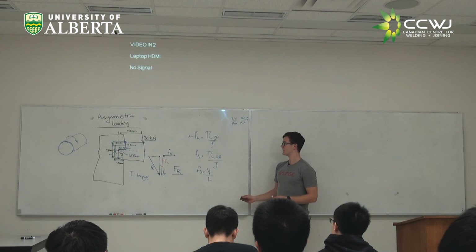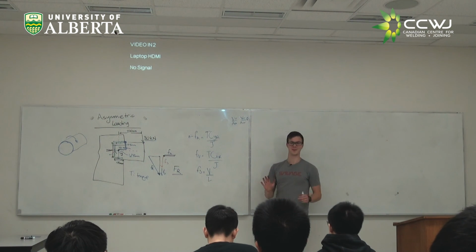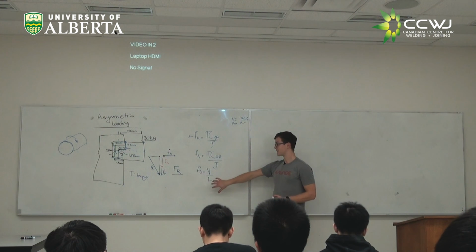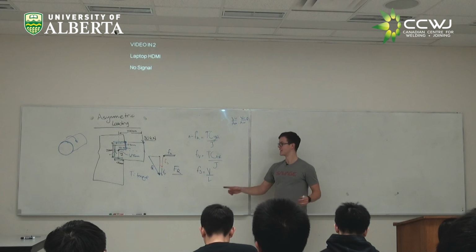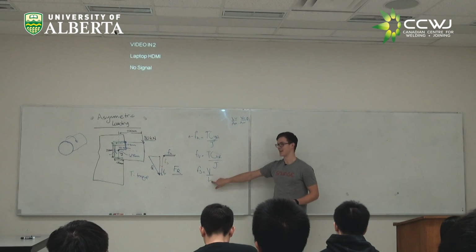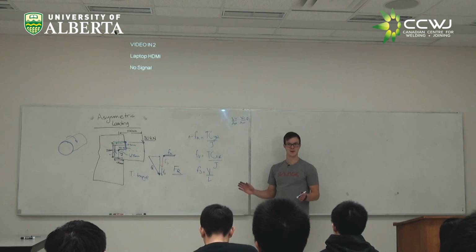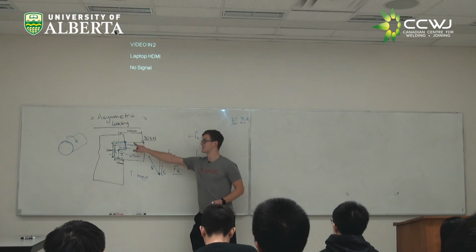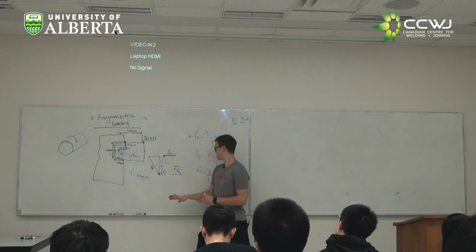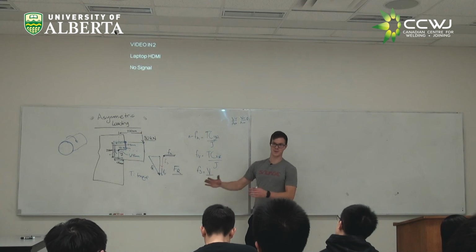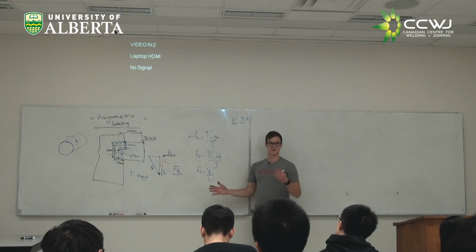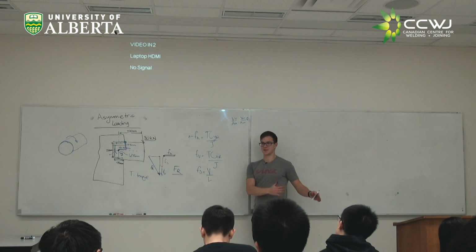I have to think about this for a second more, so I'll correct it if it's wrong, but I believe the problem with this approach, if you were to try to do a totally general approach, is we're assuming that each unit length of weld is the same. So if you wanted fillets that were different sizes up here and down here, this is not going to let you have that, where the other approach could. So it's not that one is better, it's for different situations.